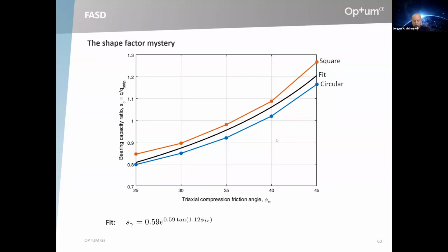So say, Kristian, as an engineer, you got a triaxial friction angle. How would you convert that? Which factor would you use? Well, it depends. I would go into my local code and see, does it say anything about it? If I'm in Denmark, it does say something about it. If not, then I would say probably 1.1 is as good as anything.